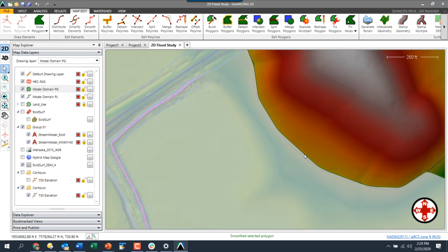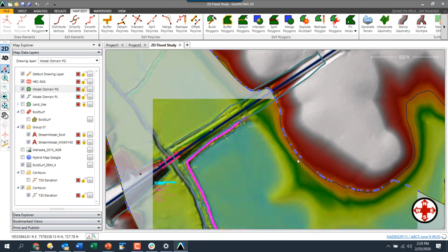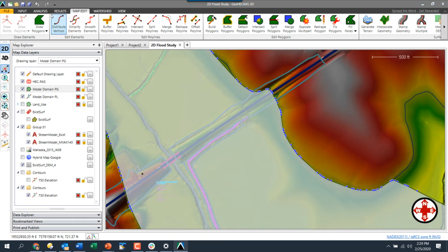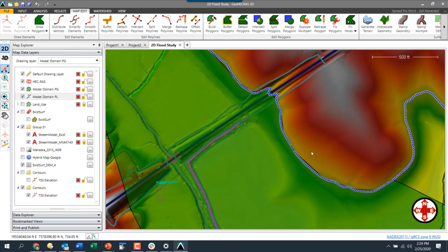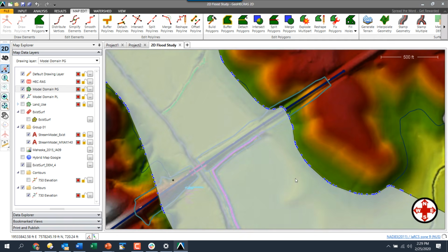No, well, it looks like it did a little bit, but let's see here. Yeah, so you can see it's adding additional vertices in there. So it's smooth. You saw it smoothing that corner in there. So you can see it's doing its job. So instead of what I had before, remember if I undo this, if I come here and select it, now we have sharp turns in there. If I go back and put those in there, come here, grab it, you can see that's not the right one, but we want to grab this one. If I press function key F4, you can see it's added that in there. So it smooths things out pretty quickly.